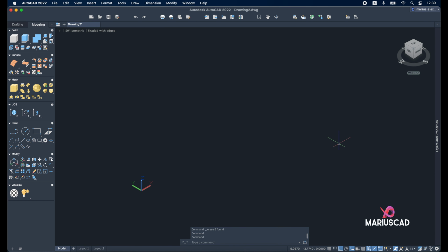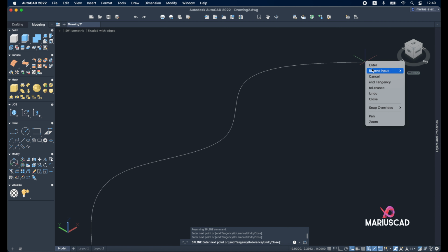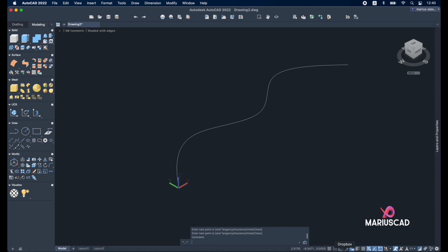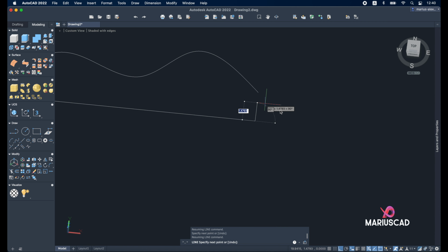The next command that I want to show you is the revolve. In order to do that, let's construct another spline, starting from the origin 0, 0. Let's deactivate the ortho command. Okay, right click, enter. Create a line again, but activate the ortho command this time. So line 0, 0, and let's make it like this. Now let's extend this part. Enter. Let's extend this part.